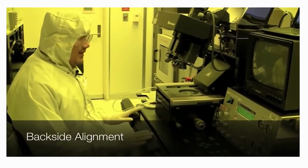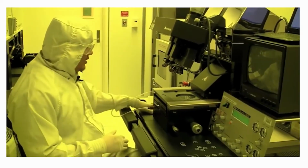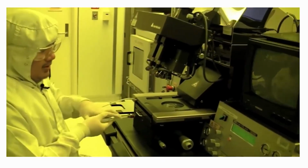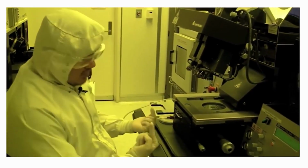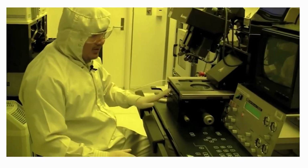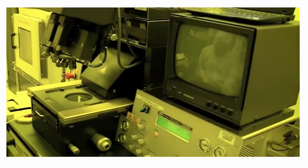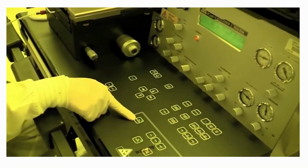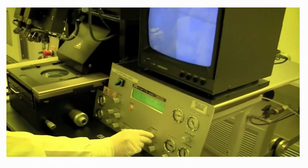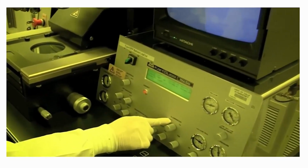We're going to be doing a backside alignment now. So what this does is it aligns features on the back of your wafer to your mask. And how you do it is with a microscope from the bottom. So the first thing we do is we have to have a mask loaded, and then we turn the screen on, and we make sure this thing says backside alignment microscope is on, so it's on. But also we need to change this to backside alignment. So it can be either a topside alignment or it can be a backside alignment.